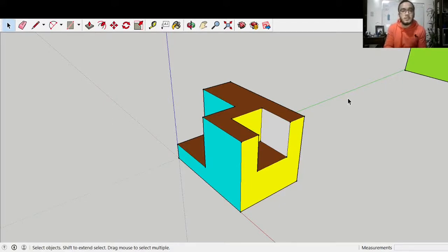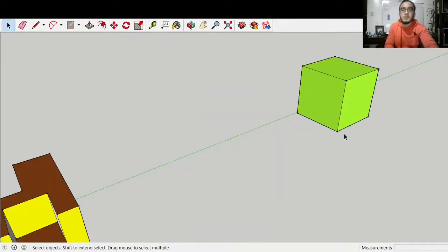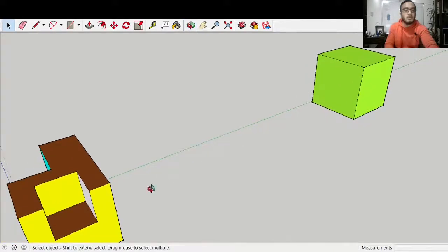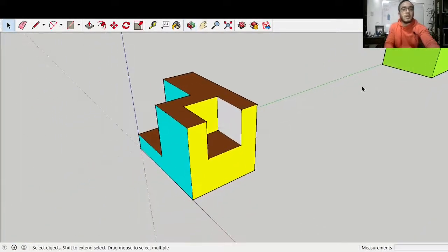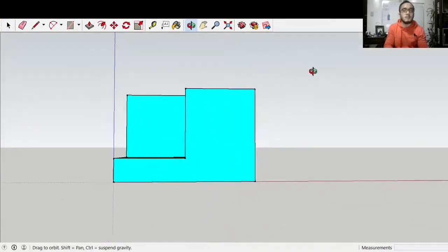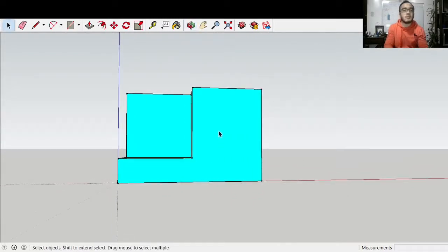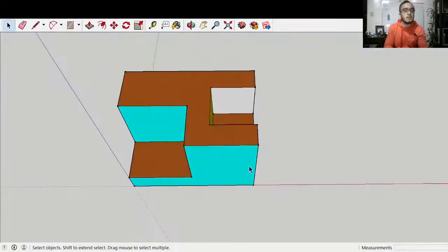But since you already know that from when we talked about the cube earlier, what we would be focusing on right now is the orthographic projection of this certain figure right here. Like I said earlier, in order for us to project a certain three-dimensional object orthographically, we must draw its front view, its top view, and its right side view. So with that being said, this would be the front view. So this blue part only is its front view. And if we would be looking at it from the top, this would be the top view.